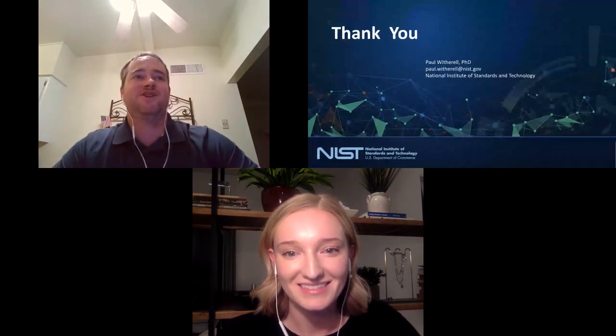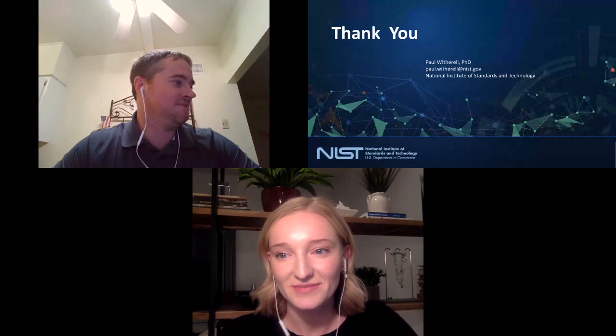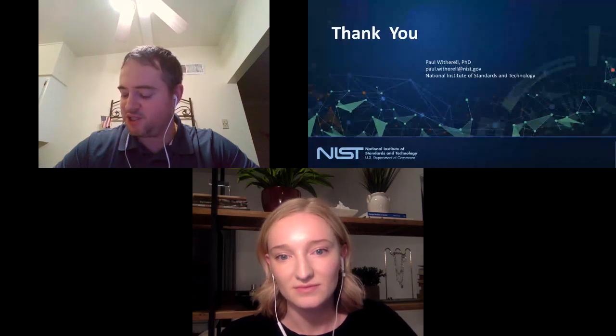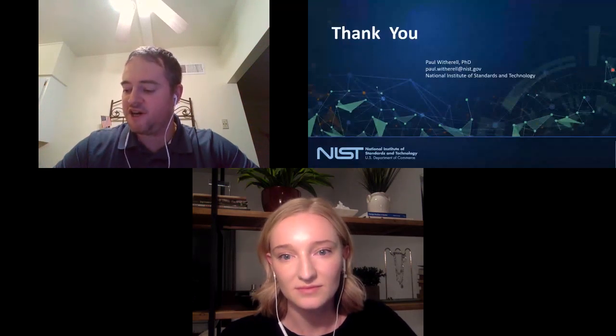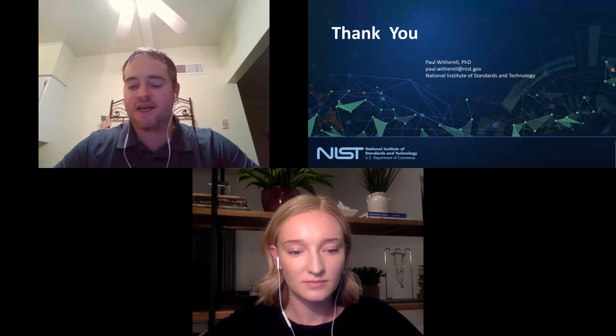That's also a great question. I think a lot of people are starting to ask the question themselves as well, because one of the things that we've seen in additive manufacturing is, because of the uncertainty with the process, we've gone into some very complex testing procedures to try to qualify things. We saw a little bit about the XCT and identifying porosity in different parts, but just because we find the porosity doesn't necessarily mean that the part can't be qualified, because we don't necessarily know what that porosity does to the actual performance of the part.